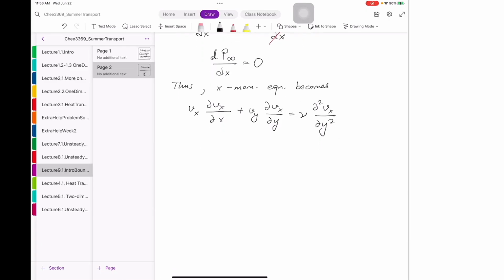We also found that the Reynolds number is equal to V infinity L over nu. As defined, we call it Reynolds L, which means our characteristic length is taken as the length of the plate, or the size of the object. And we found that it scales with delta over L to the power -2. It's delta tilde to the power -2.